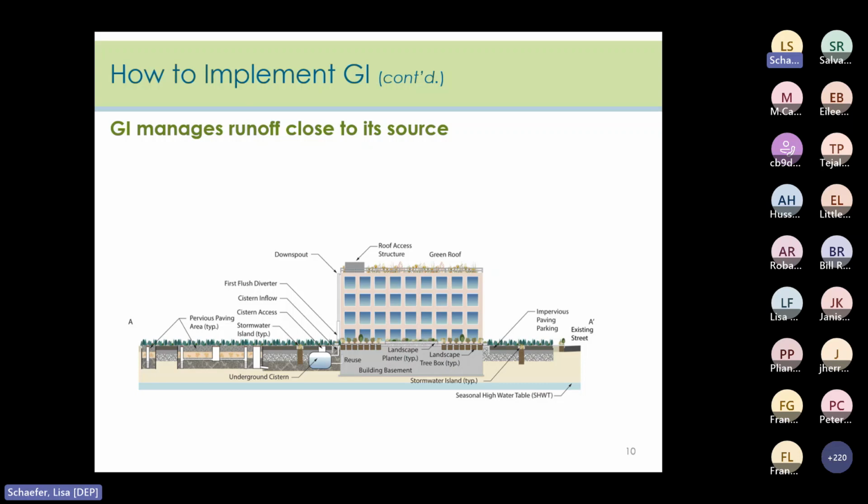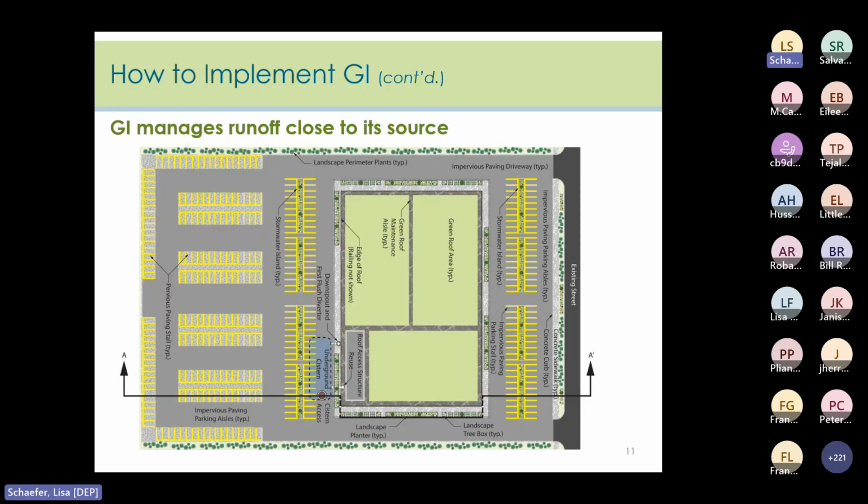However, because it's in an urban redevelopment area and was previously completely disturbed and fully impervious, groundwater recharge is not needed. Additionally, the proposed condition reduces the impervious surface, so there's no recharge deficit. All right, and as I promised, this is the plan view of the site that we just saw in profile. Now, since the existing site is so highly impervious, many of the non-structural stormwater management strategies that are required by the local municipal stormwater management plan could not be easily implemented on site.